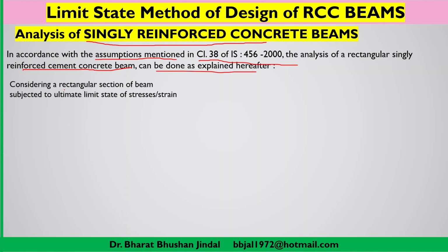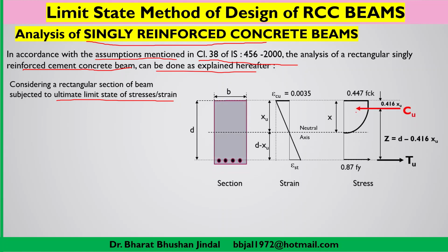Now let us consider a rectangular section of a beam which is subjected to loads, such that it will reach the ultimate limit state of stress and strain. That means in a rectangular RCC beam, the concrete will reach its ultimate stress as well as strain, and so will the reinforcement. Here you have to go through this diagram very carefully.